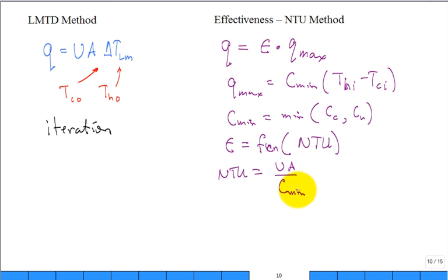So, if you're trying to, what we call rate the heat exchanger, find out the rate of heat transfer occurring in that heat exchanger, what you typically do is you go get the size of it, the area, and then the convection coefficients to get the overall heat transfer coefficient, normalize it in a number of transfer units, find the right correlation for that heat exchanger so you get the effectiveness. That goes up here, calculate Q max, and that's how you would start with the size and get the rate.